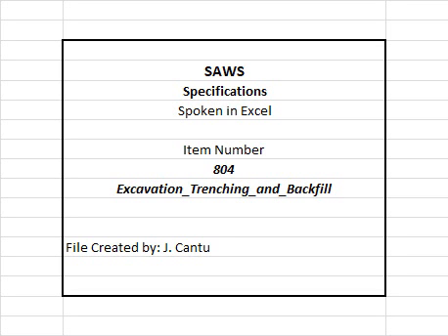G. The contractor shall be responsible for all costs associated with the proctor and density tests, and for providing to SAWS and consultant, if applicable, verification that necessary compaction levels were achieved. H. These tests shall be performed by a nationally accredited, independent testing laboratory. I. The contractor shall provide access to SAWS and to lab to the test area, backfilling test areas and provide associated trench excavation safety protection at the contractor's expense for all depths and lifts.